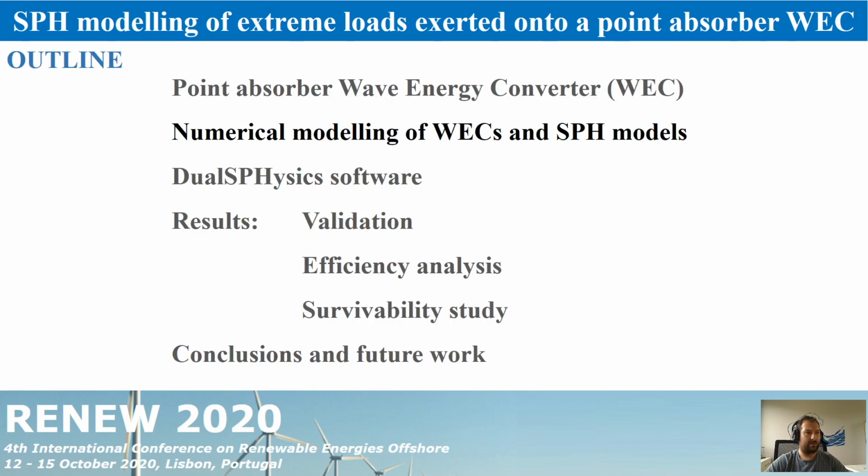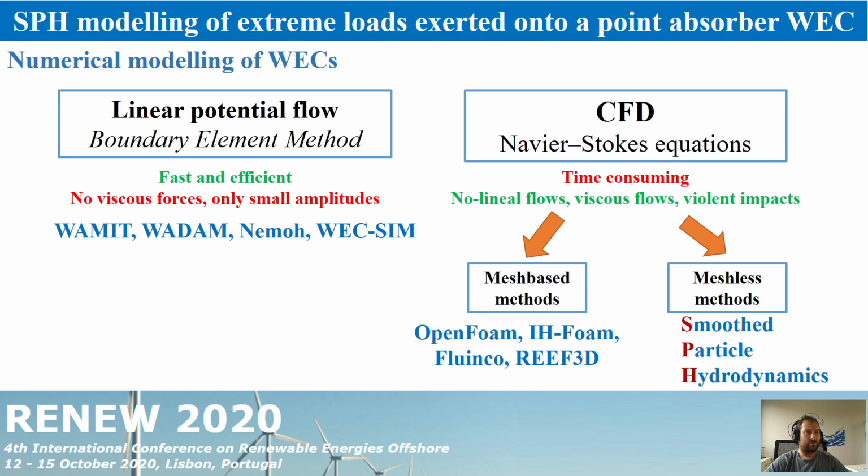Let's now talk a bit about numerical modeling of WECs. So here you can see two different approaches. The first one is based on the linear potential flow, where we are going to use the boundary element method. These methods are fast and efficient, but they cannot deal with viscous forces, and they can only be applied to study small amplitudes. Some examples are WAMIT, WADAM, NEMOH, WEC-Sim.